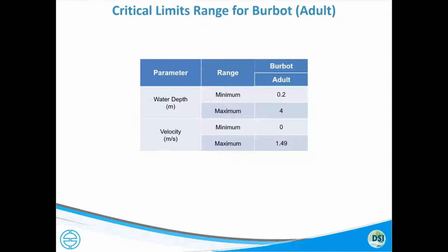It's going to look at what area or volume of water meets a criteria. You're either inside or you're outside. If any one criteria is outside these limits, then the whole cell or the whole layer, however you've defined it, is outside the limits, and it gets a value of 0. All the values have to be between the min and max in order for a cell or a layer to get a value of 1. So this is just a binary 0-1 analysis.